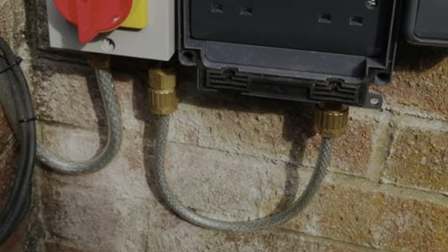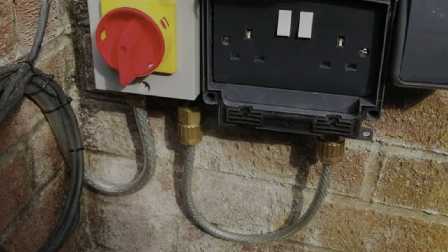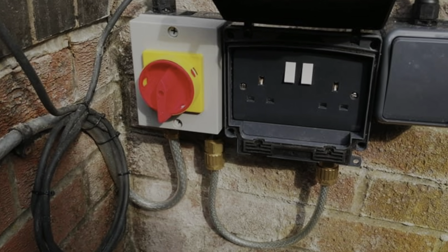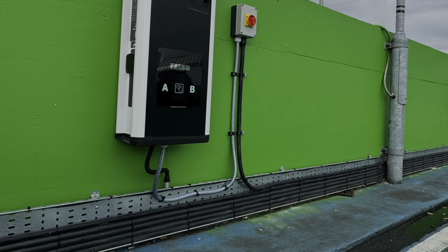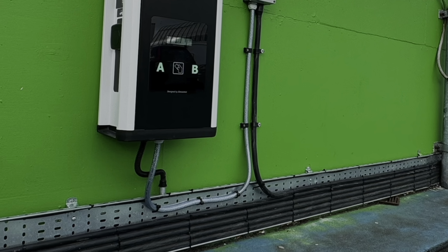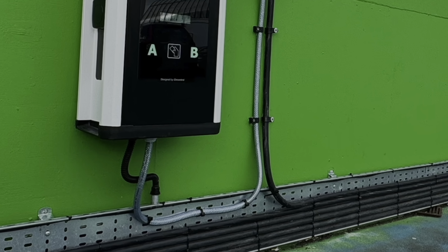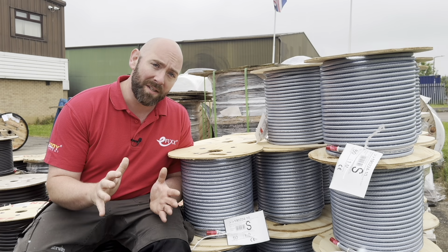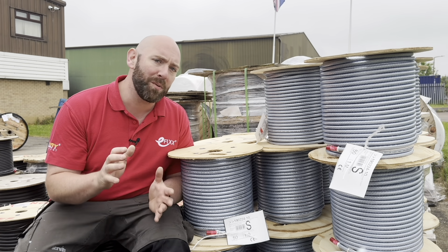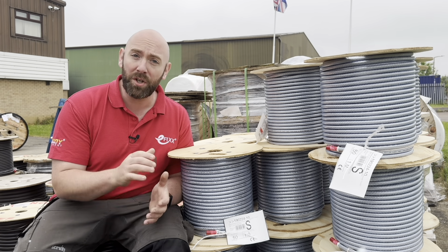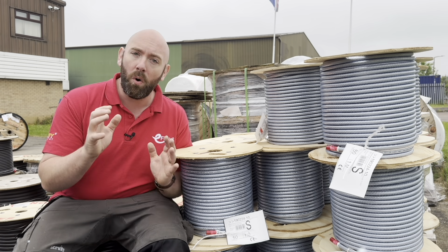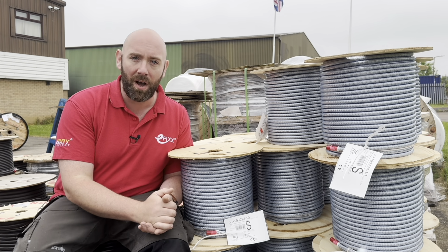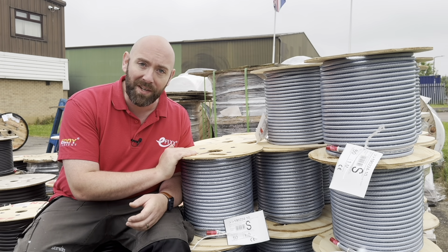Furthermore, they are not designed to carry a fault current. I've seen examples of SY cables used on EV installations, and if a short circuit was to occur, this would cause the braiding to melt and potentially cause fire due to the heat from the cable. So what's the takeaway from all of this? Well, yes, it's a very pretty cable to look at, but SY cables should only be used where they're supposed to be used. And if you're unsure, always refer back to the manufacturer's guidance and the cable manufacturer as well.